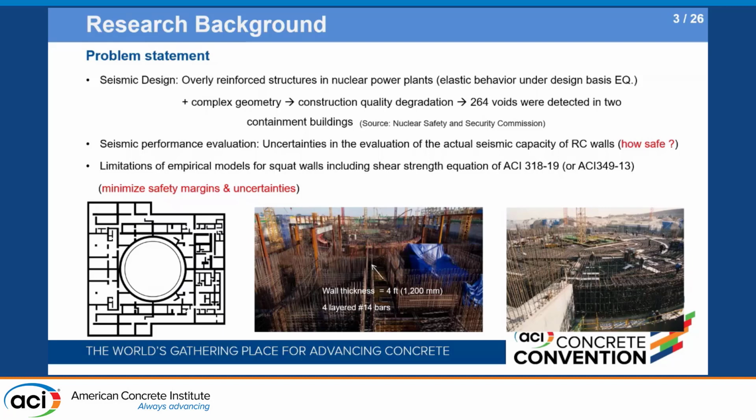In South Korea, we actually found more than 250 voids in containment buildings, which was a very big problem. From a seismic performance evaluation perspective, as I said earlier, we now have to focus on how safe the nuclear power plant is under beyond design basis earthquakes.